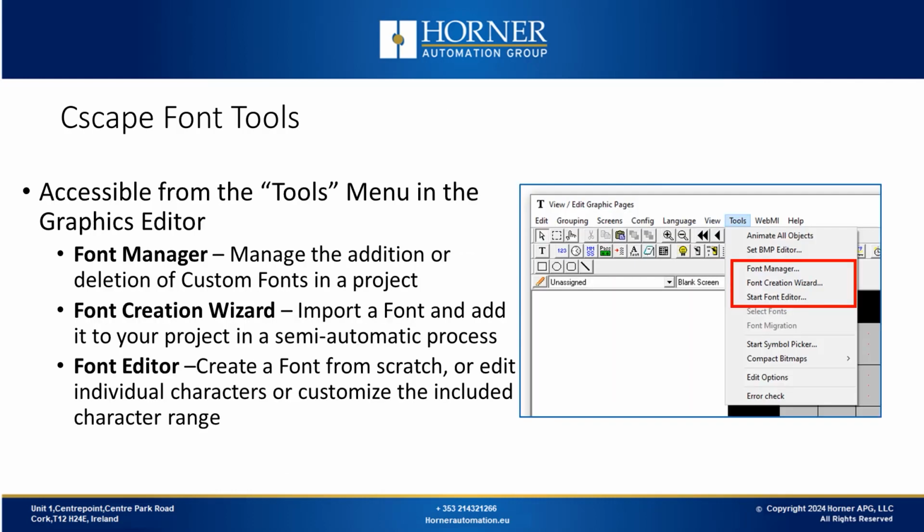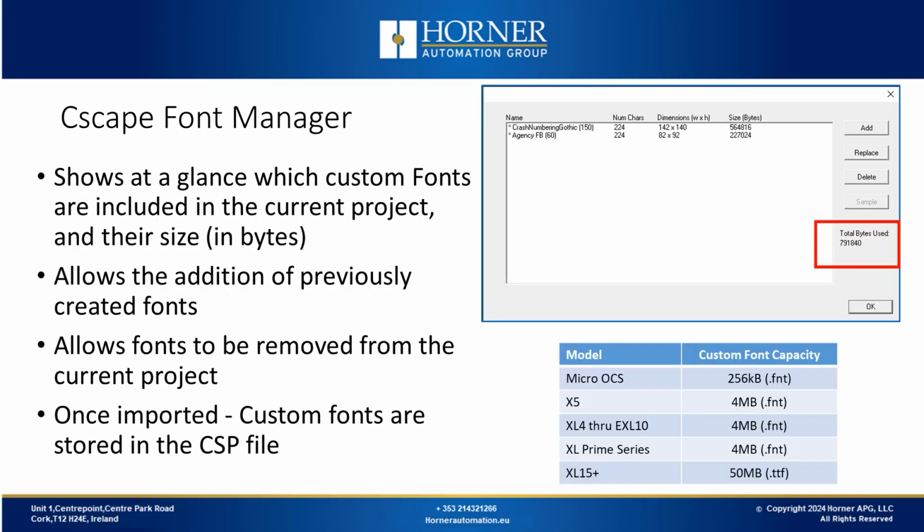We will also discuss the specific font tools included in Cscape's graphics editor to help you import and deal with fonts. We have 3 tools for this. These are the Font Manager, the Font Creation Wizard, and the Font Editor, which are all accessible from the Tools menu in the graphics editor. First, let's look at the Font Manager.